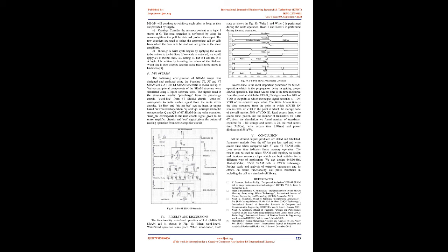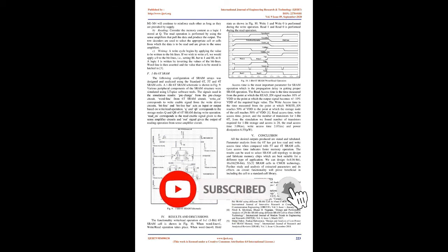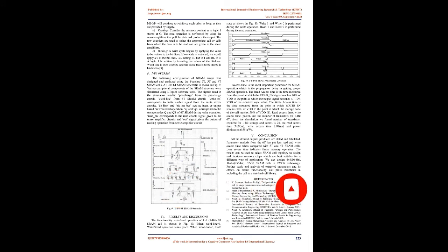Access to the cell is enabled by the word line in Fig, which controls the 2 access transistors M5 and M6. The cell also has 2 bit lines that control both the input and output of the data from the cell. The first bit line, known as bit line, holds the same value that is stored in the cell. The second bit line, known as bit line bar or bit line not, holds the inverse of the value that is stored in the cell.